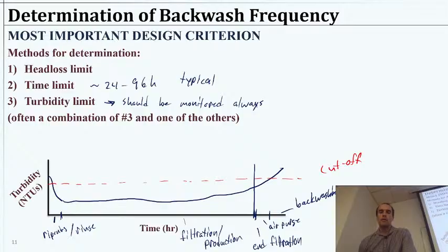Now, of course, the turbidity after that point we're not really tracking it. We're not producing any water. As soon as we cut it off, we recognize we're not paying attention to that line anymore. So past the cutoff, that line is imaginary, like what would have happened. So just keep that in mind. We'll cut it off. We're no longer monitoring turbidity because we're not producing water. If we had left it going, it would continue to increase.